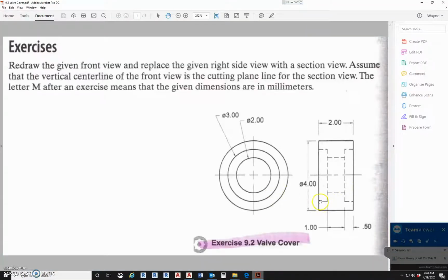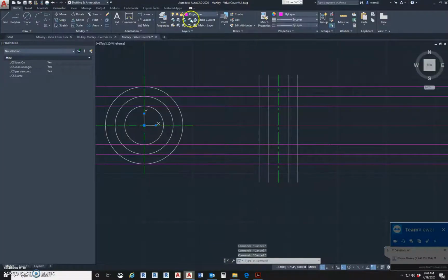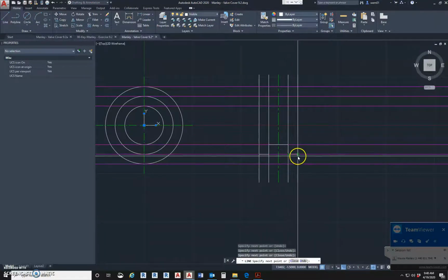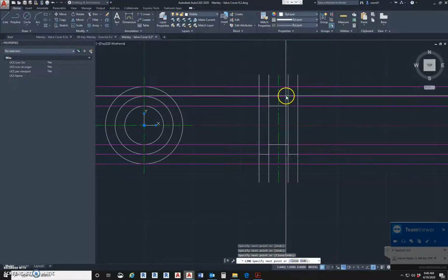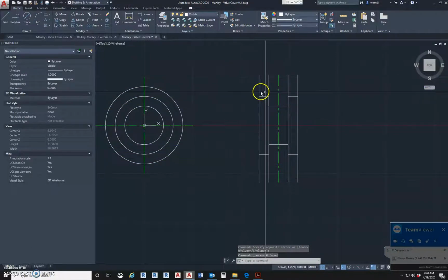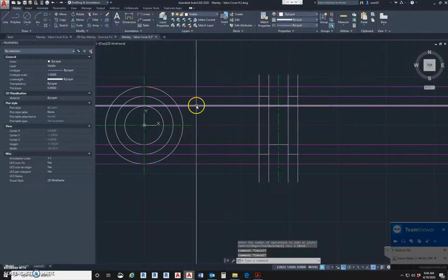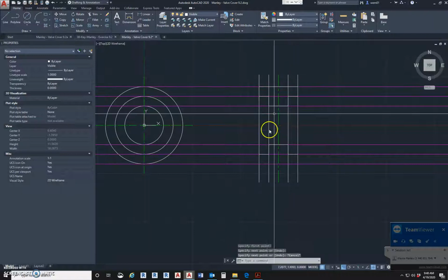Now we're going to look at this. It looks like the line goes in, up, over, just like that. So let's do that. Change our layer, and now you could do the same thing up here. You could draw it again or mirror it. I'm just going to draw it. So now we've used up all our projection lines, so we can get oops, no, we did not. We forgot the top line here. Can't forget the outside shape.